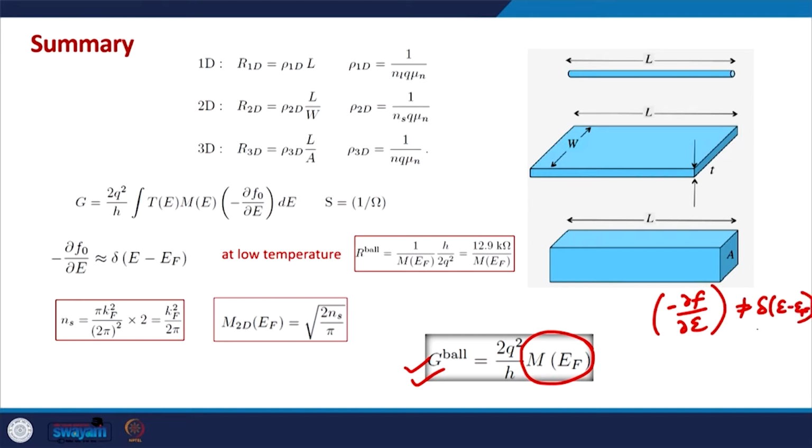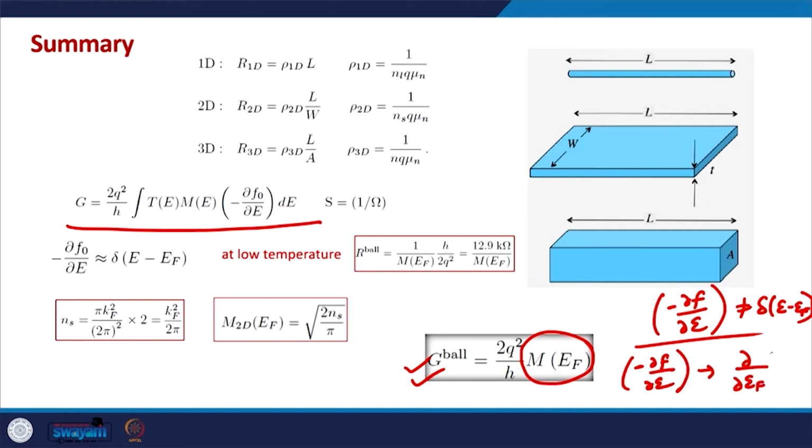this integral needs to be evaluated properly, and now this integral also has a derivative with respect to E, which can be converted to derivative with respect to EF. Okay. And after doing calculations at room temperature for the conductance, we realize that we come across a special type of integral functions. Those we defined as Fermi-Dirac integral functions.